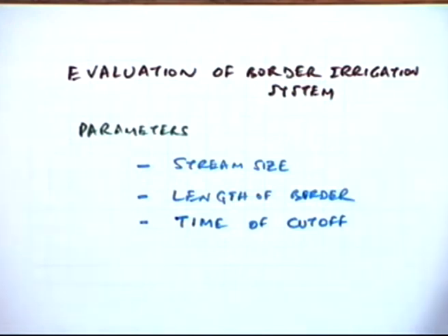This will be related to for how long you should supply water, when the supply should be cut off, and how it is influencing the various other related parameters. The time of cutoff will also decide the lag time, that is, for how long the water which has accumulated over the surface will take to recede or to deplete.